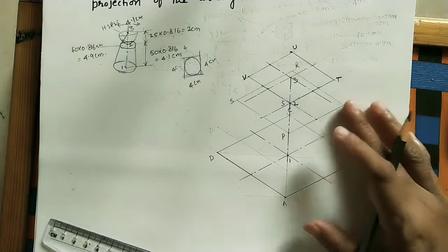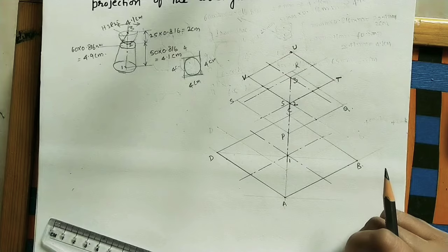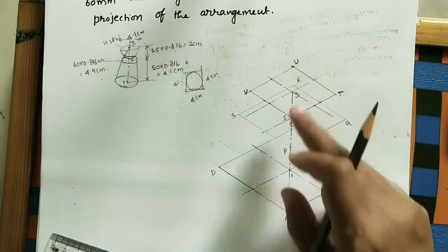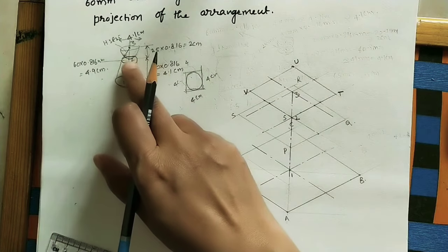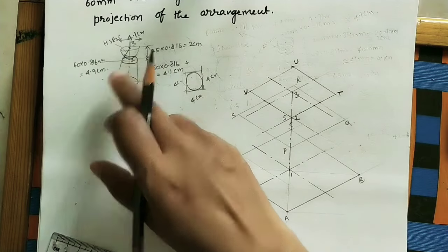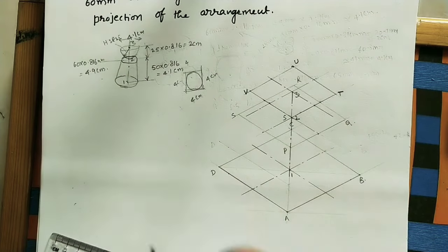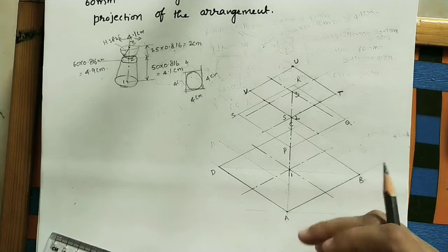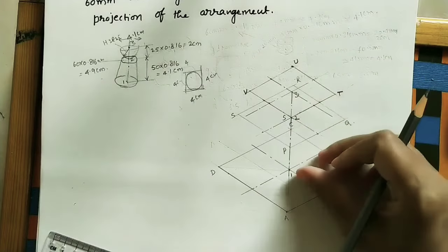Here we will follow the 4 center method for doing the ellipse in all the 3 rhombus. So this rhombus is for getting the ellipse of the top surface, and this second rhombus is for getting the ellipse of the top surface of the frustum of a cone, and this rhombus is for getting the ellipse of the bottom surface. Here we will follow the 4 center method. I will explain for one rhombus and I will follow the same rule for these 2 rhombus.